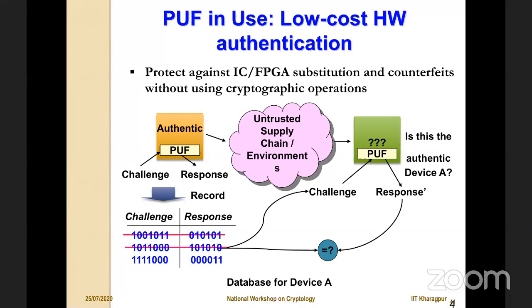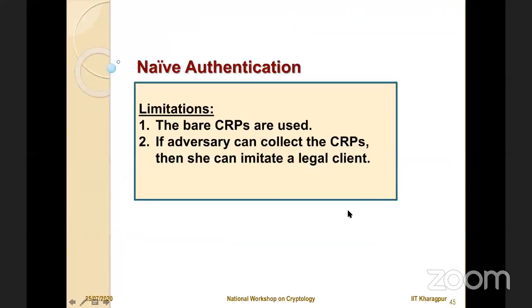On the other hand, there is another category of PUF which is called a weak PUF. The idea is that it is only used for generating a secret key, and the key is never seen by the adversary. There are different classes, like SRAM PUFs and so on, which I will not get into, which are used only for generating the keying material. These are called weak PUFs. For a weak PUF the challenge space can be small, simply because it doesn't have the problem I just mentioned. On the other hand, it is more challenging to develop strong PUFs, which also need to be machine learning resistant.